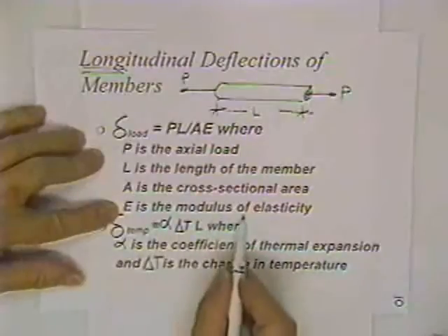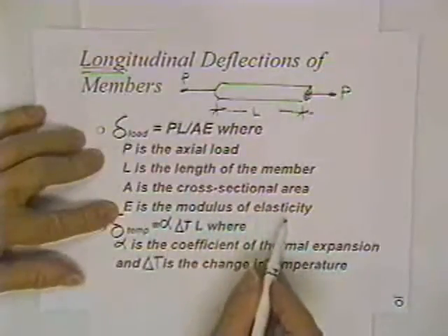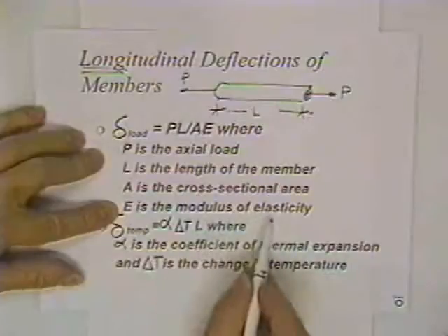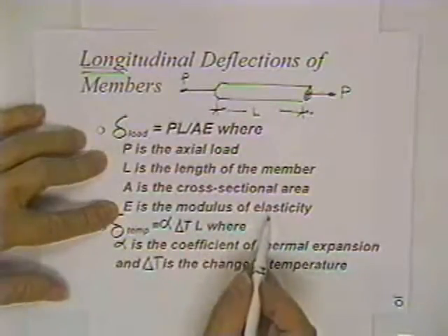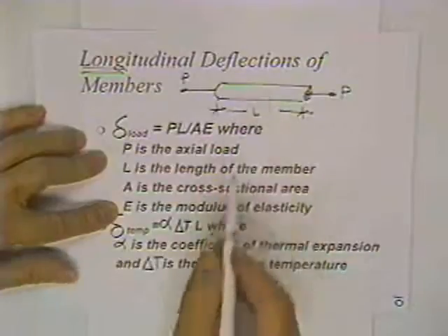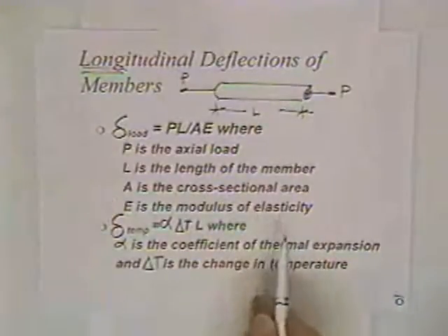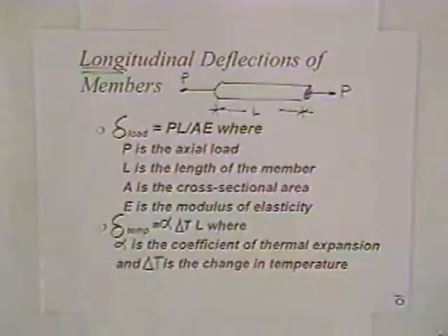And E is what they call the modulus of elasticity of the material. Those numbers are in the reference handbook. So if it says it's steel, you simply look it up in the book. Just check right quick, in your book, it's on page 32 for steel and aluminum. And that's about the only two materials they'll be able to use on the quiz.